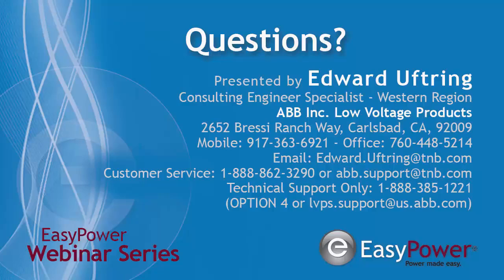Electronic trip unit and a relay. A relay just basically opens and closes. The electronic trip unit actually has intelligence built into it so that it's monitoring the Rogowski coils that we have in our breakers, or the CTs, and it's making decisions based on the voltage, the current, and everything that it sees.